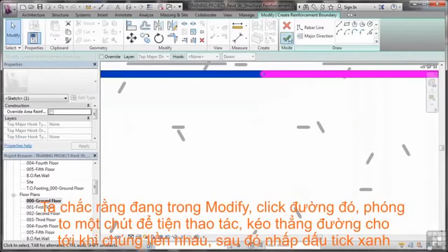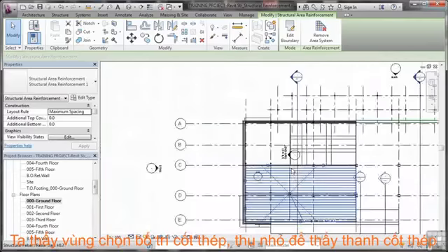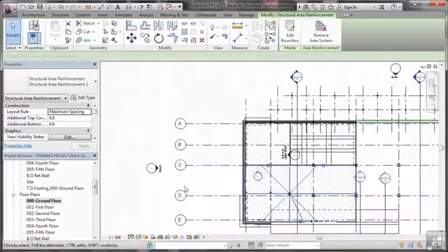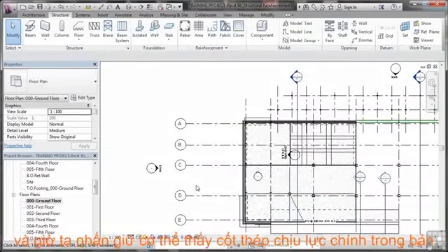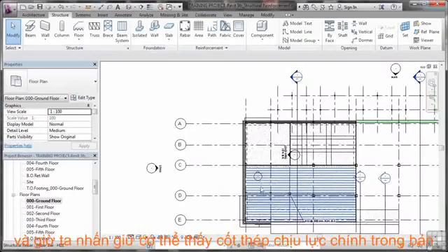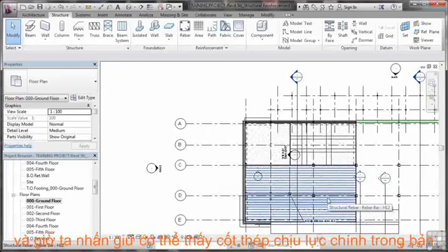Then when I click on the tick, that'll place the reinforcement for me. If I zoom out now, my rebar has now been placed. So I can hit escape to deselect, and I've now got a reinforced concrete floor foundation slab. Now if I hover over that, you can see there's the reinforcement in both directions, and you can see it's done the whole slab for me.